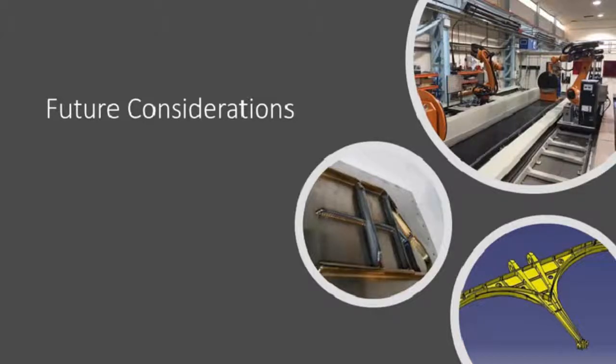In summary, compared to conventional manufacturing, the general advantages of ALM are the capabilities in design and development of products. The ability to produce highly complex parts without tools whilst gaining a decrease of production costs is wholly achievable. By its nature, ALM is well suited for low volume production. Hence, affordable and high-complexity individual products can be manufactured.